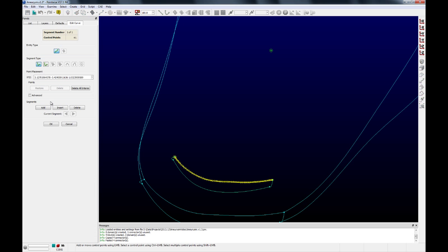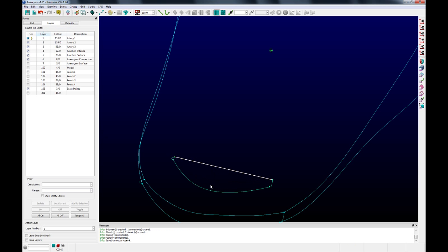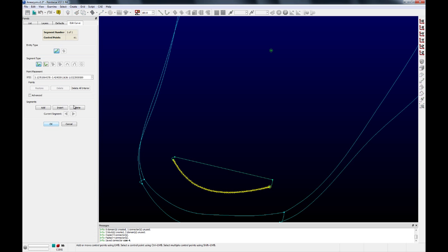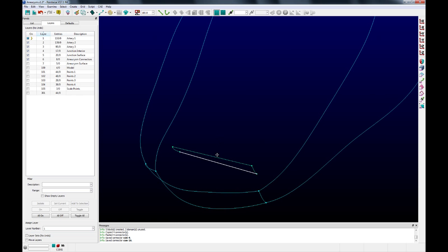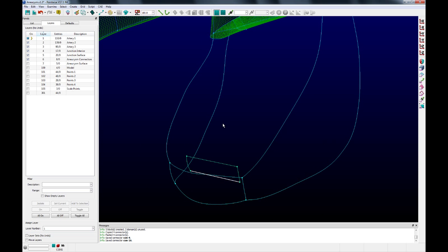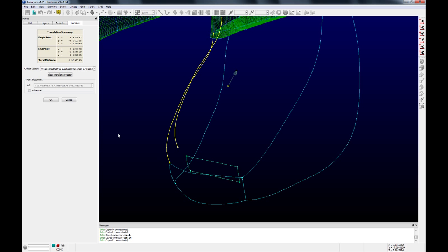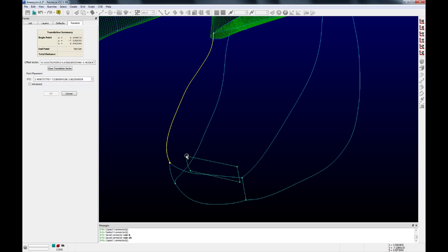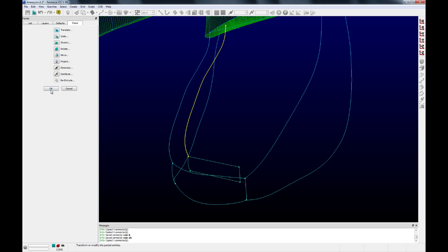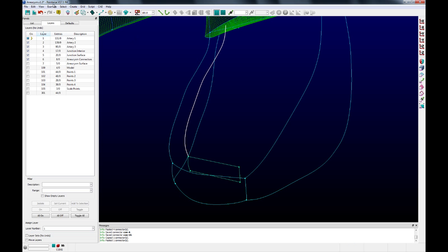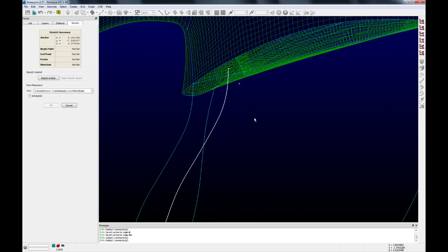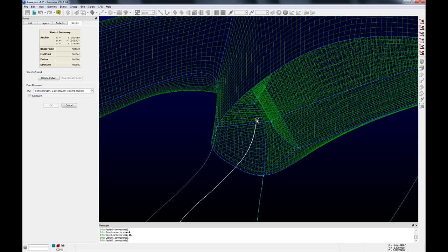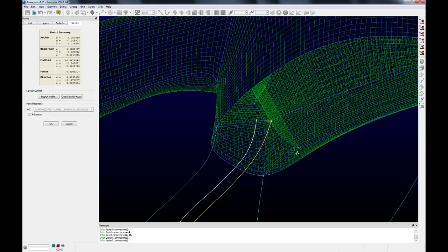So we'll go up to Edit, Curve, and then delete all interior points. We're going to repeat the process over here on the other one: Edit, Curve, delete all interior. The next step is going to be very similar to creating the inner OH topology on the artery. We're just going to select this curve, copy, paste, translate, and we're going to clear the old translation vector, specify a new one, select OK, apply a transformation: edit, transform, stretch, select our anchor, select the end of this newly created connector, and then select the topology we want to match up with.